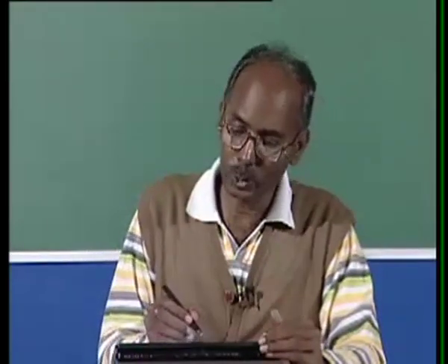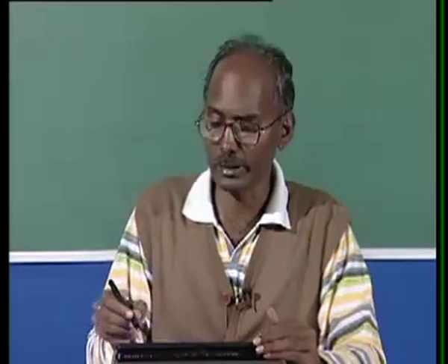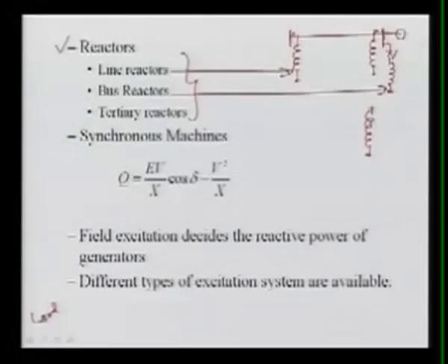Another is your tertiary reactor. There is a possibility that here we are having a transformer, and this transformer will have another tertiary winding, and if you are connecting the reactor to the tertiary winding with some switch here, then it is called your tertiary reactors.